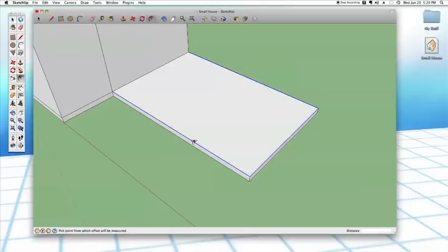Oops. There we go. And now when I drag in, you'll notice it looks like it's doing the same thing, but look over here. It's not offsetting that line because I didn't have that line selected. It's basically just giving me the walls on the sides that I selected, not giving me an extra wall over here. So this is perfect.